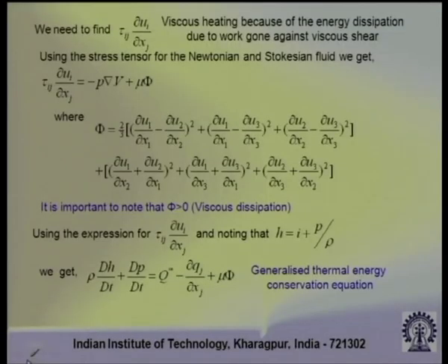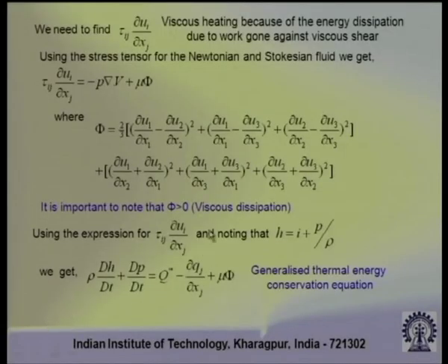So, when we convert the equation from internal energy form to enthalpy form, we require to utilize the well known relationships in thermodynamics. So, what we do is we write H equal to, where H is the specific enthalpy, equal to the specific internal energy plus P by rho, that is pressure into specific volume, that is pressure by density.